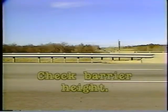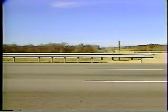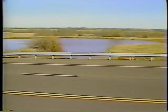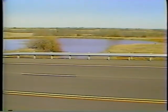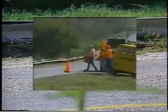The height of the transition section barrier is very important. It must be correctly positioned at each end to match the height of the barrier it will connect to. The different systems around the country may vary, however, basic repairs are the same. The following repair crew demonstrates their technique on this W-beam strong post system that's done its job, and it's now up to them to put it back in service.